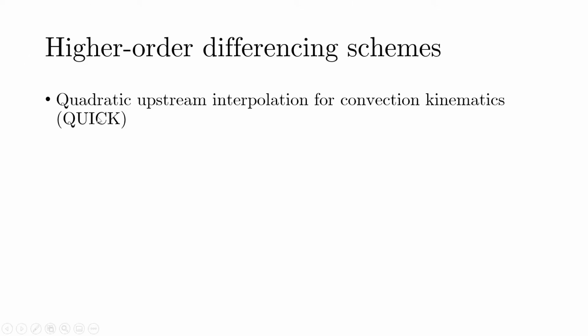So all the effort in CFD is towards handling that convection term, because that's a non-linear term in the governing equation. So the QUICK scheme is another effort to mitigate that problem, and that is why the name, Quadratic Upstream Interpolation for Convective Kinematics, comes into the problem. So that is about the QUICK scheme here.